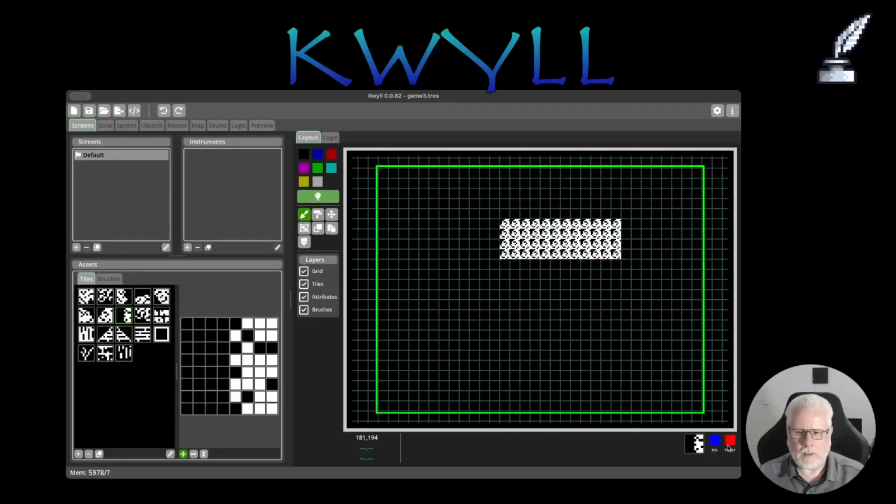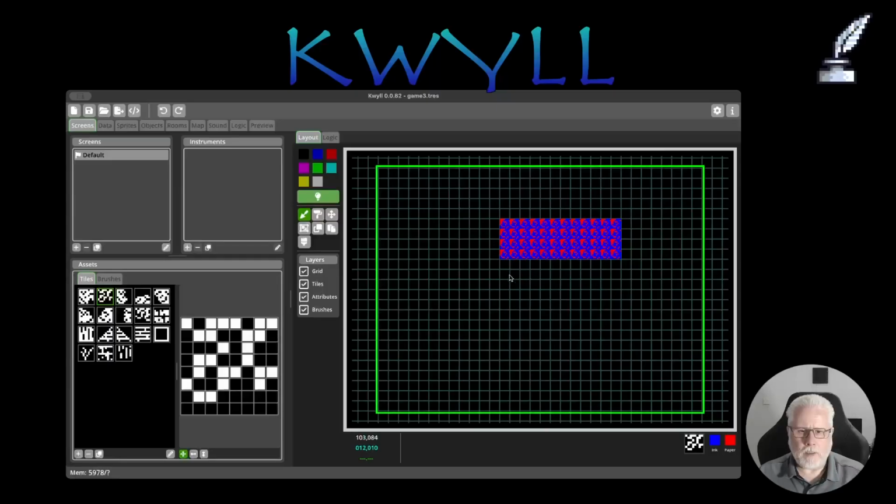And these are the colors that you'll be painting with if you choose the roller. You paint with the roller and it'll paint tile attributes over those tiles. You have the trowel, which basically pastes tiles. In each case, the left button places, the right button deletes. So if you're in trowel mode and you push with the right button, it deletes the tile at that location. And if you're in roller paint mode, it'll delete the attributes at that location with the right button.